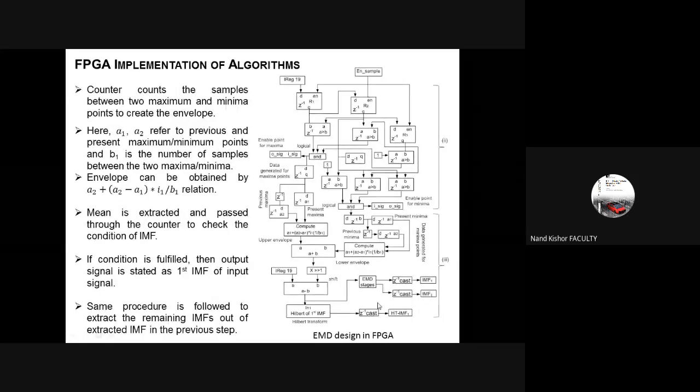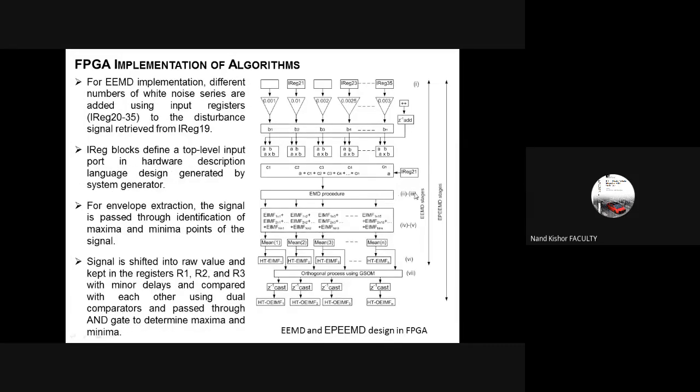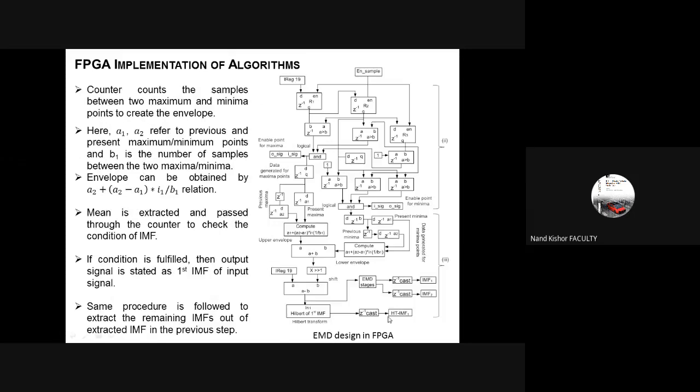Similarly, this slide indicates how we have developed the basic EMD technique in the FPGA, which I have referred to here. So if you refer to steps two and three, it is the EMD procedure in this block. So it is this one here. In the EMD technique, what we are interested to know between the two samples, as I said, is that we want to have the envelopes.